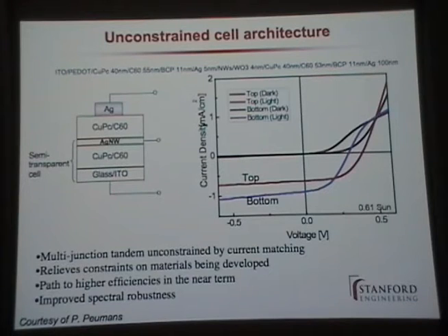So I can make a multi-junction cell, and you know multi-junction cells from regular 3-5 photovoltaics. You stack them all up, and the current goes through the whole stack. So there is a current matching requirement there. All the cells have to be able to carry the same current. Otherwise, you're limited by the cell that performs the worst, because that will be the bottleneck for the current to go out. And in fact, the other cells are just dumping current to the cell that performs the worst.